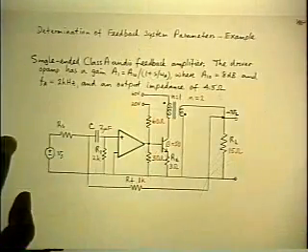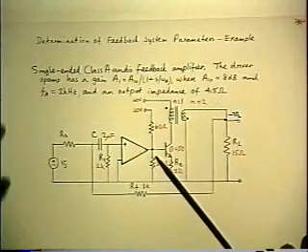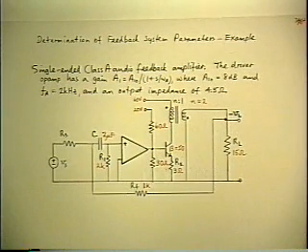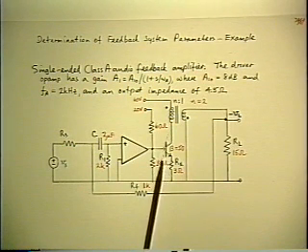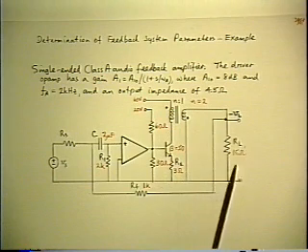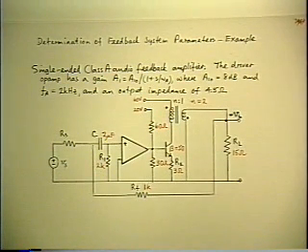Well, so much for the generalities and block diagrams. Now it's time to get down to a specific circuit example. Okay, let's do a circuit example. A very primitive little audio amplifier. Single-ended Class A power output stage, transformer coupled to a 15 ohm load.